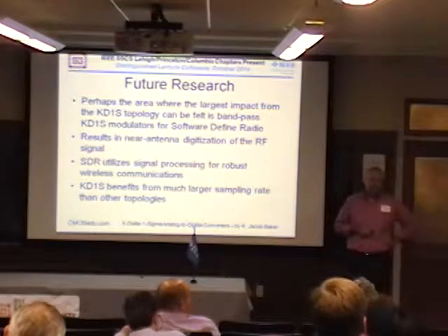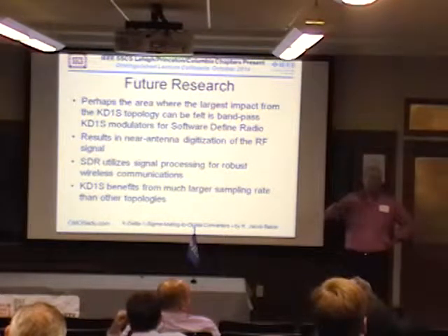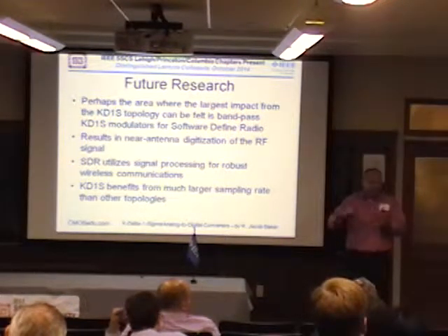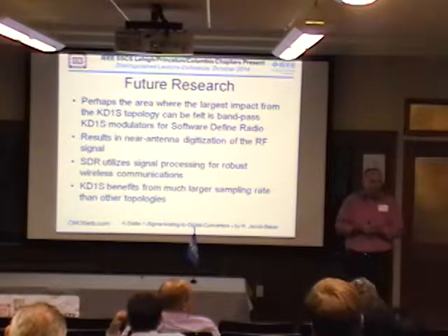I think there'll be a benefit because each time you sample onto one of those capacitors, you're sampling noise, and that noise is then sent to the feedback capacitor. However, if the noise is random and Gaussian, and not some funny spectral or funny probability density function, if you average 8 of those sampled noises and they're truly random, it should reduce the kT over C noise by the number you sample.